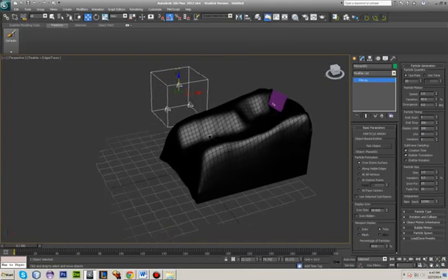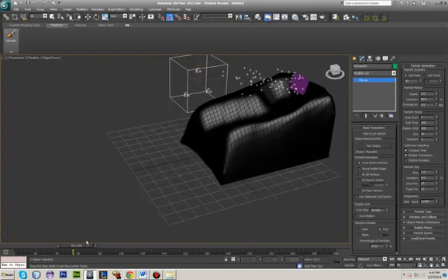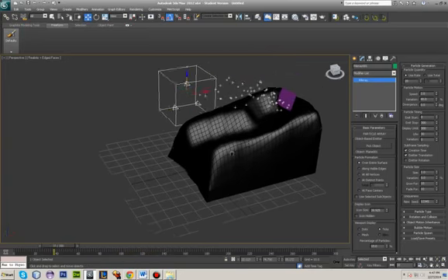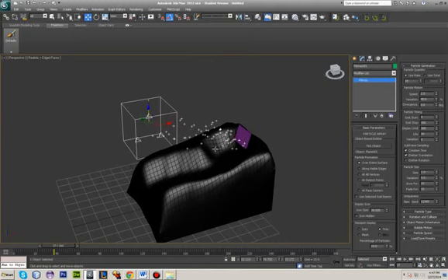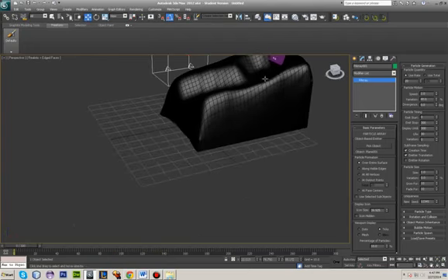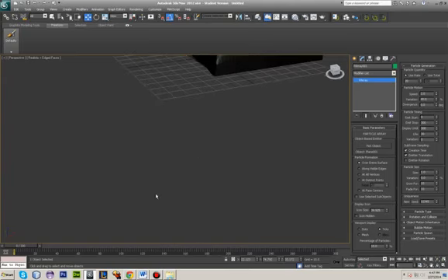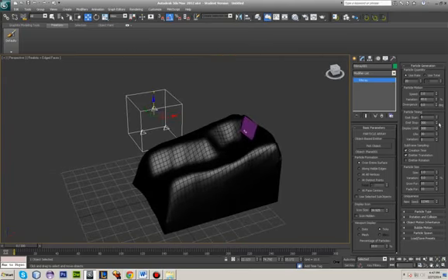And life is basically how long each particle will be visible for. Right now it's set to 30, which means that from the moment it's generated, for 30 frames it will be visible, and then it's going to disappear. So I want the water to fall down and around here. I'll have to play around with it. For now I'll set it to, I would say, 55. We'll see how that works later on.